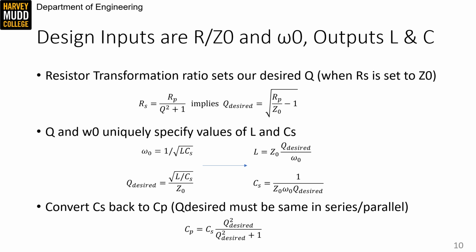These design equations aren't too bad, which is nice. However, this derivation is specific to the L match we used. So these design equations won't work for every L match. You can see that because things would start going wrong as early as the first line if we had to do a series to parallel conversion instead of a parallel to series conversion. So you'll need to redo this process for different networks.